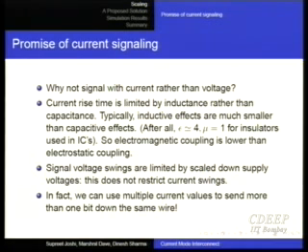Then I'll have a 2-bit D to A conversion at the transmitter and a 2-bit A to D conversion at the receiver. Now I'll use a single wire, and because the input impedance is 0, the voltage will still remain 0, and depending on whether I receive 0, 1i, 2i or 3i current, I will now be able to receive 2 bits.